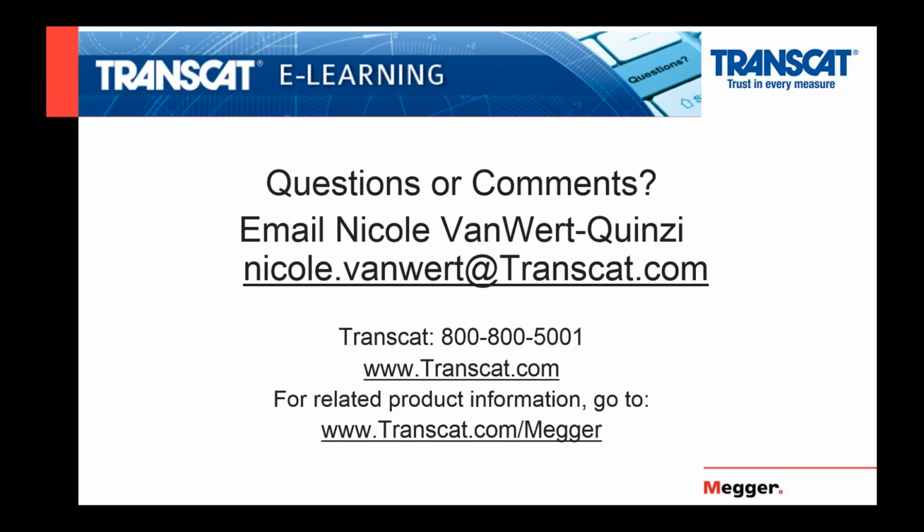Can we do equalization on any type of batteries? Again, that is a battery manufacturer question. Be careful with equalization charge. Some manufacturers of VRLA batteries may tell you not to equalize them because you are going to be generating heat in them. Now remember, in a VLA battery, we can add electrolyte. In a VRLA battery, we cannot add electrolyte, so you have to be extremely cautious. If you're going to do an equalization charge for one of them, go to the battery manufacturer because they may tell you do not run an equalization test on these particular types of batteries.